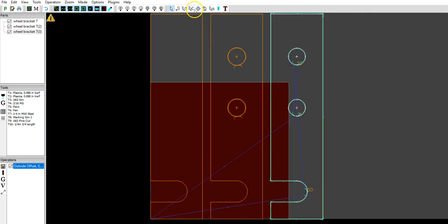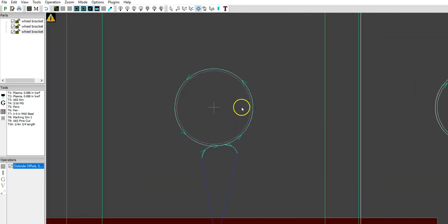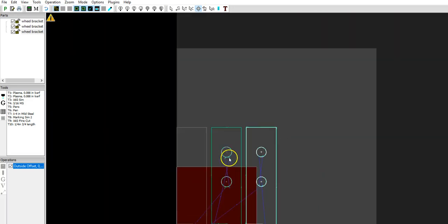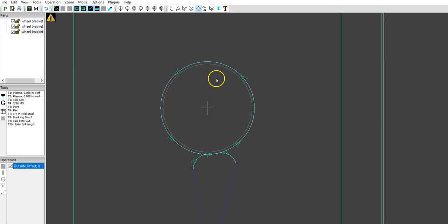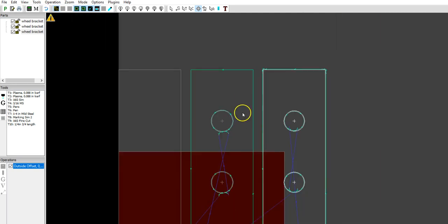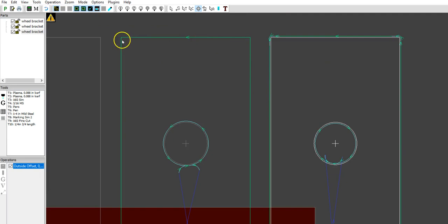And let's go ahead and compare and contrast all of this here. We'll go to nesting tool and we can see all the different files. So this second file, where we didn't fix the outside shape, but we put two inside shapes, and I use that loosely here because the outside isn't actually a shape. So from here we can see that it's trying to cut from the outside of the shape because this is an actual shape. Now because lines don't have an inside or an outside, this is actually cutting along the line.